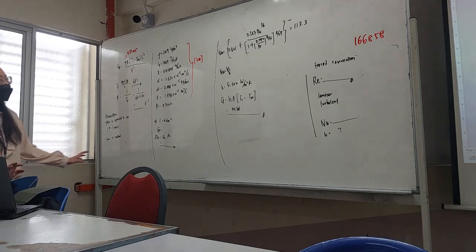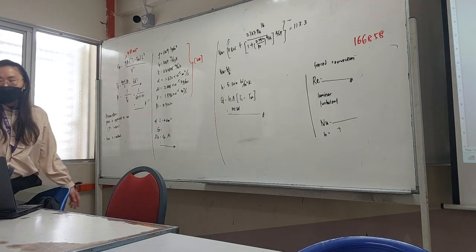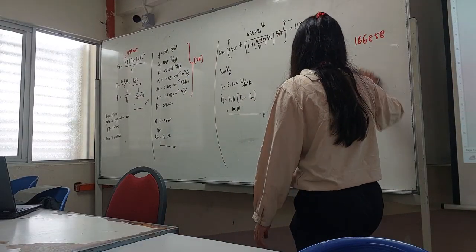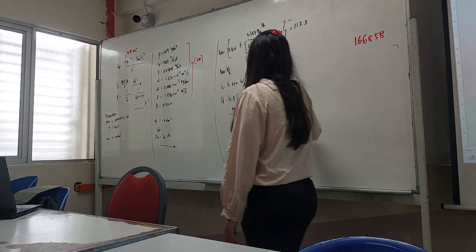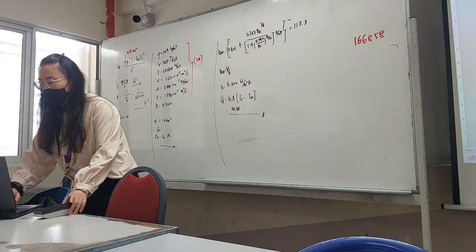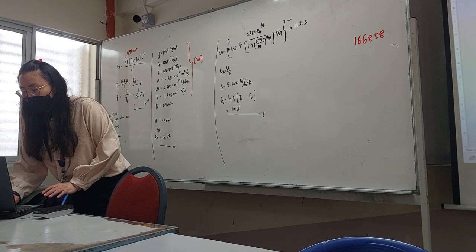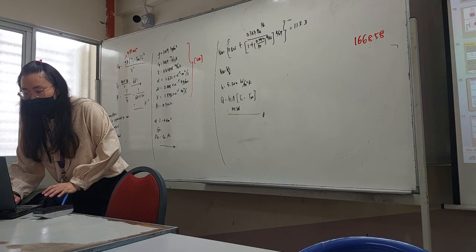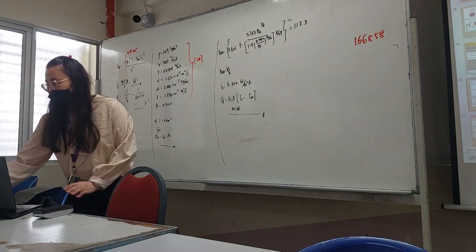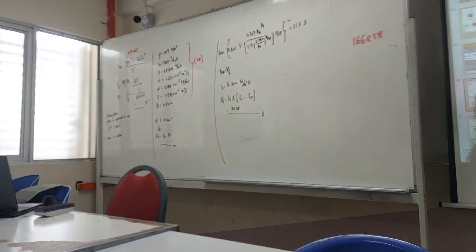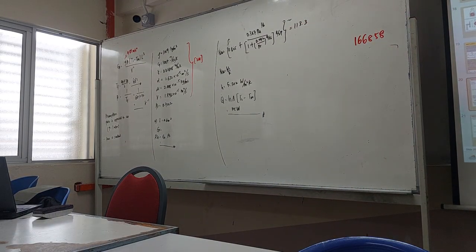Okay, so the first part is very simple. The second part also applies the same concept. Now the hot surface is facing up. Again we have the formula. Horizontal plate, hot surface on top. So you need to calculate the Rayleigh number, and see where it falls.